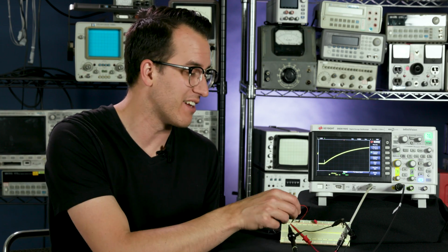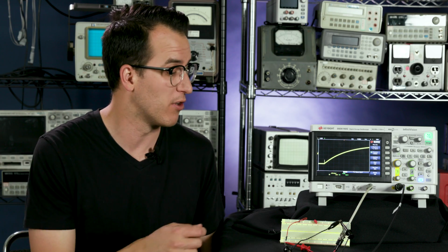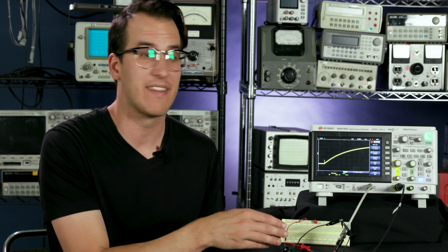So ultimately what this means is you have to be very, very careful in your systems and your electronic circuits to make sure that you're not using crazy long ground wires, or if you're going around and using an oscilloscope, especially a very high bandwidth oscilloscope using some high bandwidth active probes, having a long ground lead like this is going to put too much inductance into your measurement.